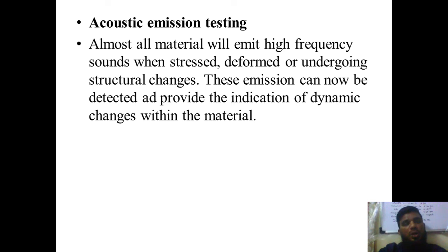Once you make a part, you are going to install it into the system. If it suddenly fails at that time, it will create a large amount of loss. But sometimes, because of repeated application of load, such as fluctuating stresses, or because of fatigue, the material may fail. These kinds of things can be studied using non-destructive testing, so you should have a clear picture of the importance of destructive testing and of non-destructive testing. For a new material or a specimen, we go for destructive testing. If it is a real life application where you are continuously using the part,